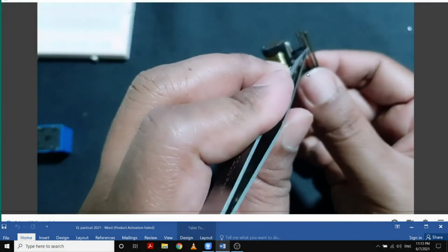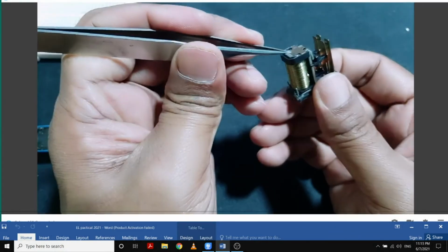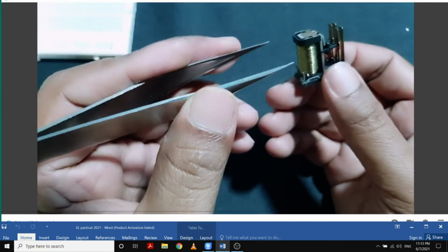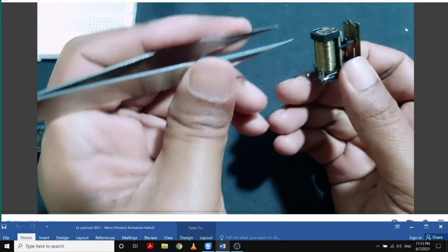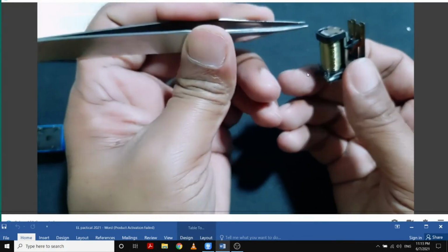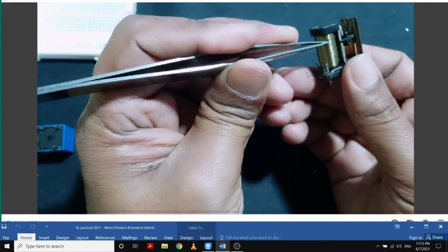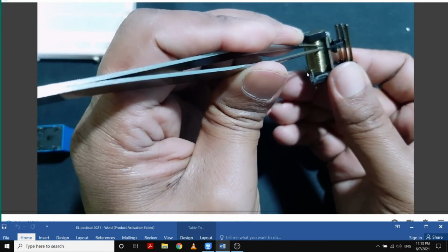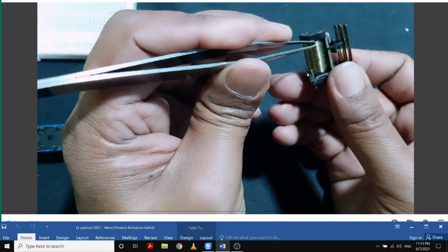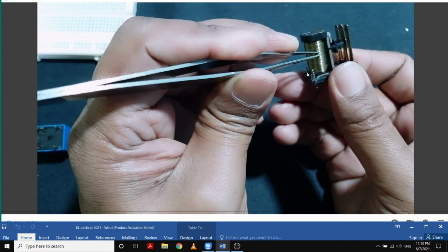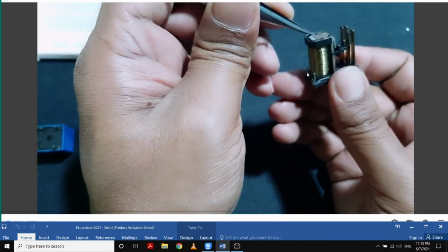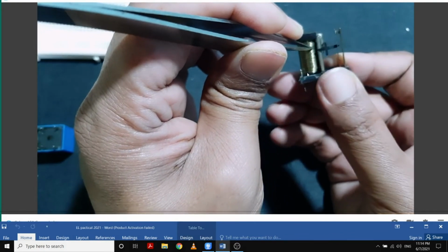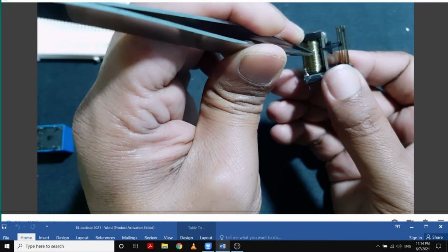So this connection will be established when you, in the circuit, just push and release the button, then this will get a high amount of electricity, and the connection will be established, right? Then gradually the current through this coil will be reduced, but this will hold until the electric current gets to some critical level.